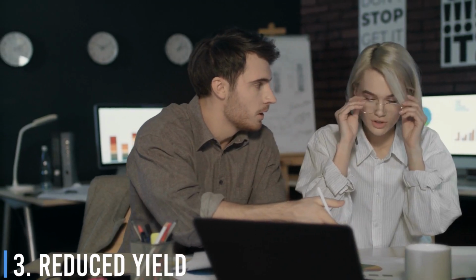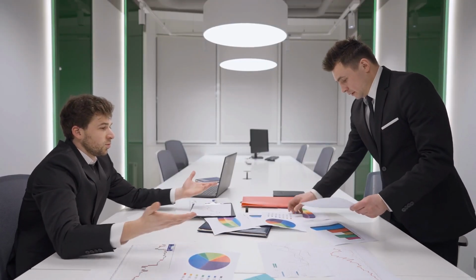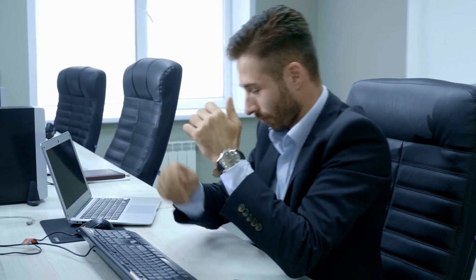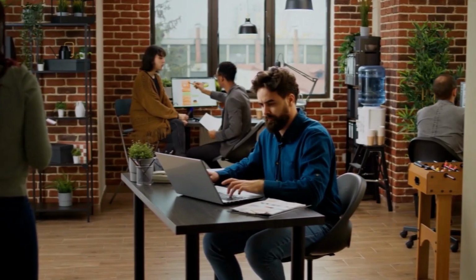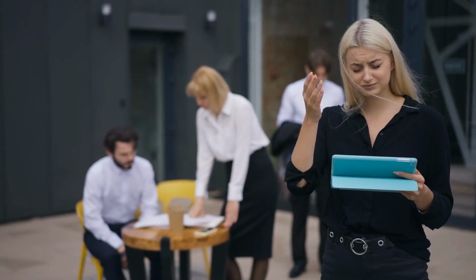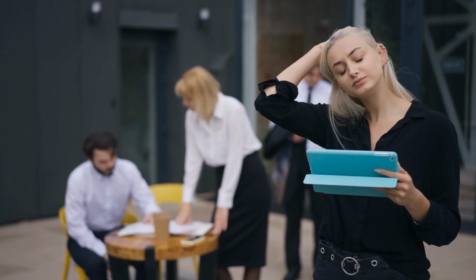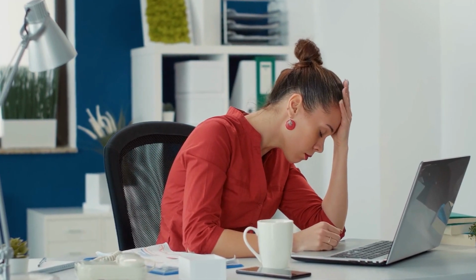Number 3. Reduced yield. Reduced yield accounts for defective parts produced from startup until stable, steady-state production is reached. This includes scrap parts as well as parts that can be reworked, since OEE measures quality from a first-pass yield perspective. Reduced yield can occur after any equipment startup. However, it is most commonly tracked after changeovers. Reduced yield is a quality loss.